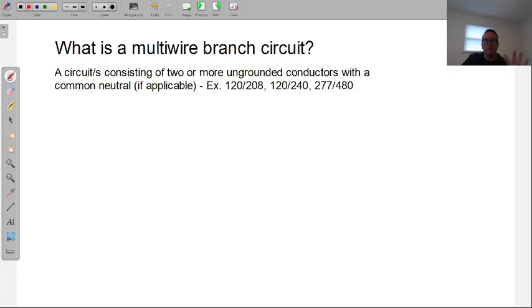All right, so again, now as you're writing this out, I'll just kind of catch us up to where we're at. We understand what a circuit is. We've got an idea of it. Complete from the power source back to the power source. A branch circuit is originating at a panel or some power source. Again, we'll mostly call that a panel. Probably 99% of the time a breaker. And then ending up at a load.